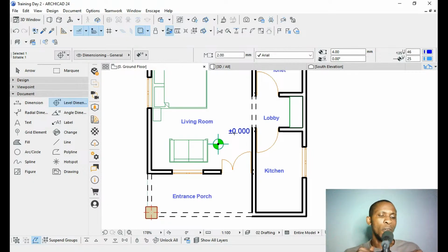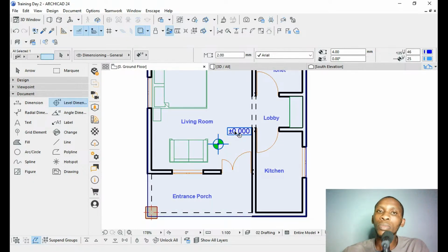From the exterior part of the building, let's say this is my base for the exterior. If I want to go into the building, I'll have to step up 450 millimeters. I want to tell someone, for construction, that this level is higher than this other one. So this is what I use. Plus minus 0 for this particular space, and I'm using plus minus 450 because of the slab we use here.